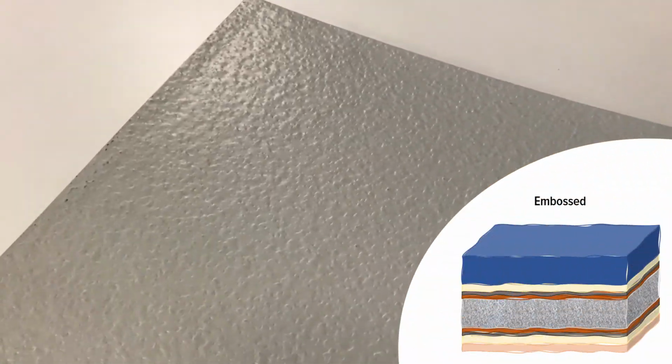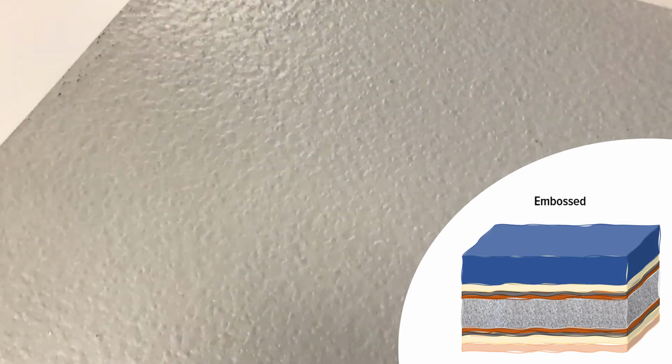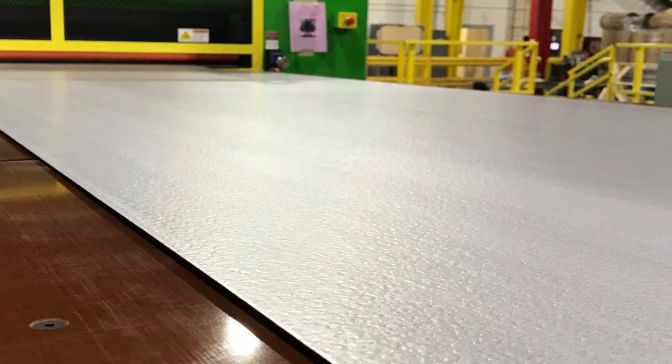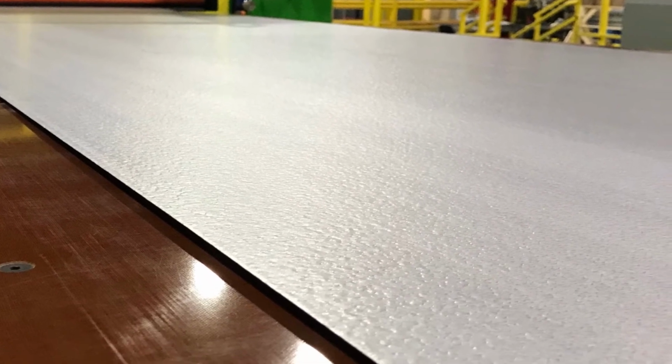While not a finish, embossing is typically performed on site at the location where the material is painted. Embossers work by passing the metal through a set of rollers which press the pattern into the metal. Unlike painting, embossing physically alters the shape of the metal. As these rollers are large and heavy in order to impart the pattern onto the metal, the number of embossing options offered is usually limited. Stucco or wood grain are the most common, and that is why for many applications, painted finishes offer greater flexibility.